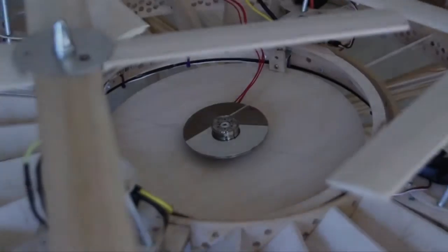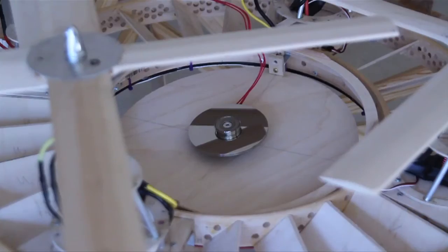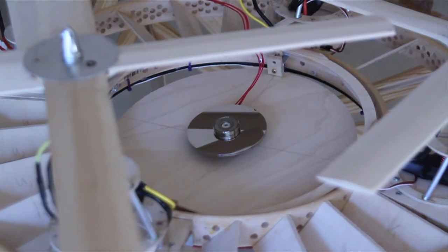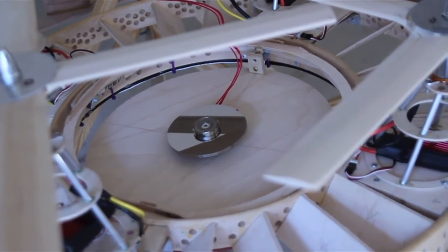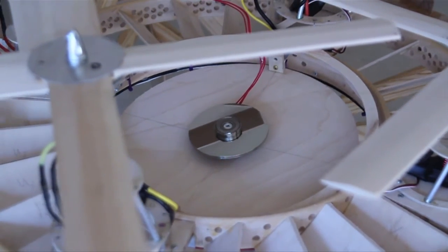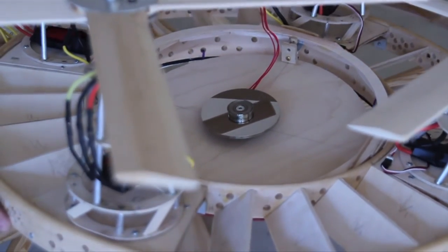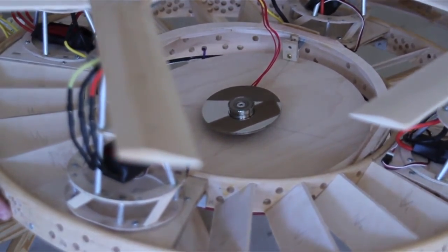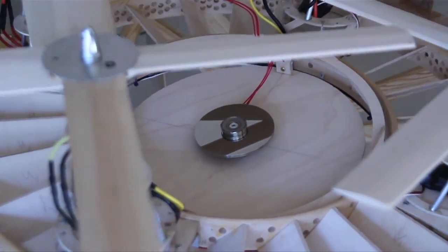Here you see the gyro in action. We used an old hard disk drive because it is precision balanced and can spin at speeds of 5,000 rotations per minute, which gives us plenty of angular momentum. The precession due to gravity aligns the spin axis to be vertical. As I tilt the drone, the 2 degrees of freedom gimbal remains horizontal. It is against the horizontal plane of the gimbal that the sensors will measure our pitch and roll angles.